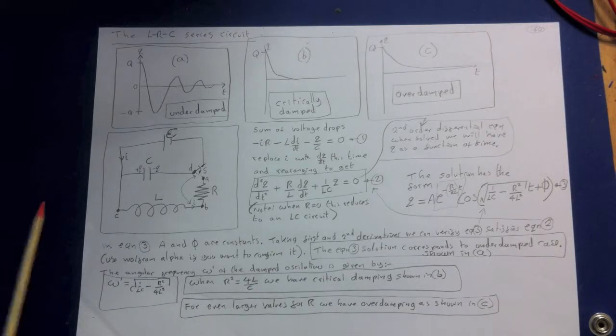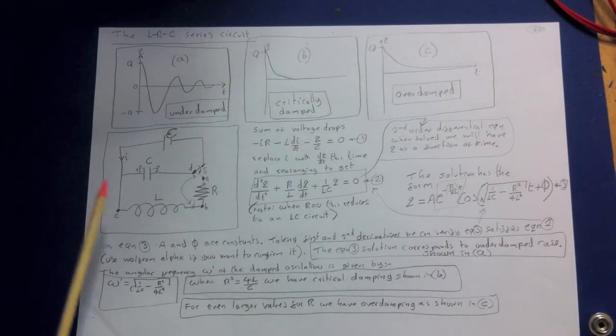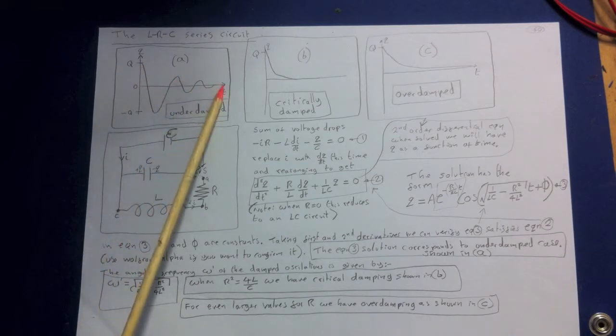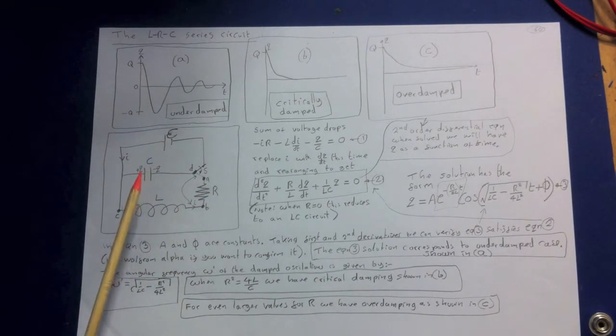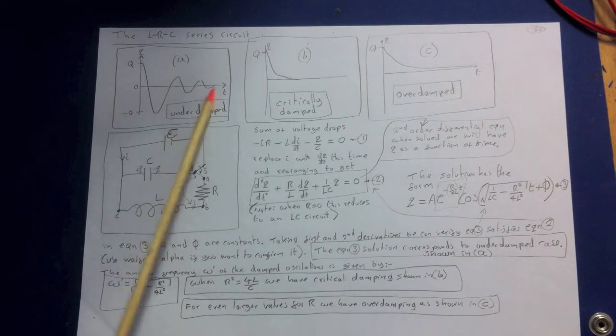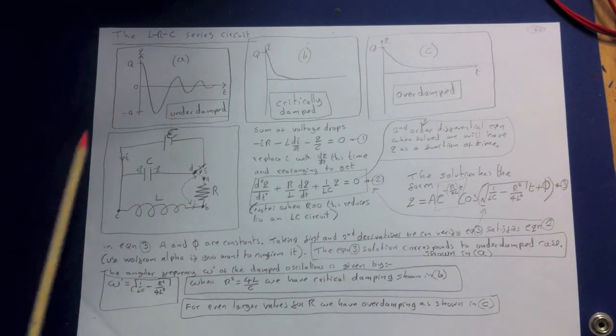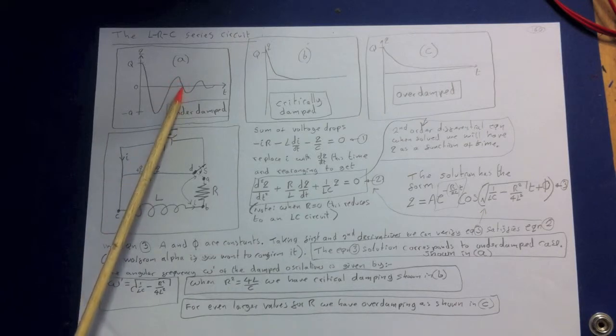In the same way, the energy of the capacitor when the magnetic field has decreased to zero is still smaller, and so on and so on. So you can see that you end up with this happening. Every time an oscillation occurs, the R will dissipate a bit of energy. The next oscillation, it'll dissipate a bit more. If the resistance R is relatively small, the circuit still oscillates, but with damped harmonic motion, as I've just described. And we say that the circuit is underdamped, so we call that the underdamped condition.